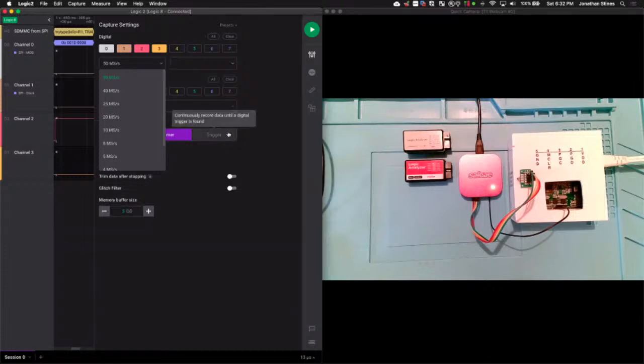Typically, when you're looking at UART, SPI, and stuff like that, amazingly enough, the speed is often not even as high as the chip can go. Like on UART, I've seen interchip comms where the chips are designed to drive at over 3 million bits per second, but the developers had it set up to communicate at 9600 baud.